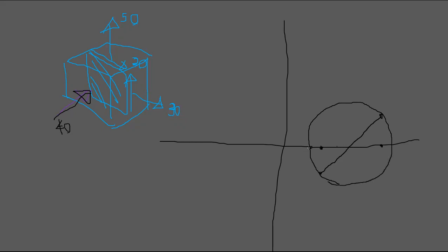So on that plane you can find the principal stresses, right? Because these are not the principal stresses on that plane, there is a shear stress. So that means you can angle this element such that there will be a plane in xy. So these are in-plane stresses. Okay, this is the out-of-plane stress, so you mark the out-of-plane stress. This is minus 40 and 0. Why? The shear stresses are 0. Again, it's the principal stress, right? Then okay, so from this element, you can find these two values.